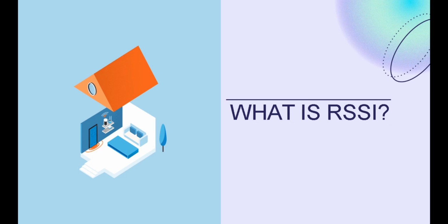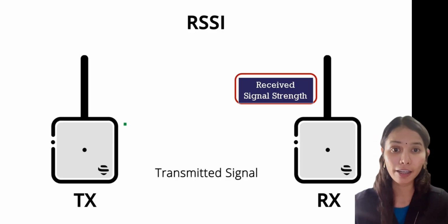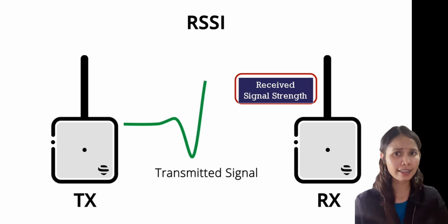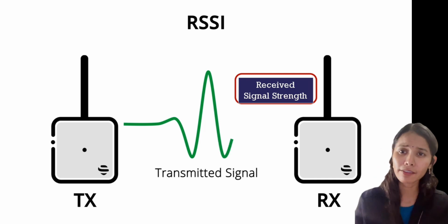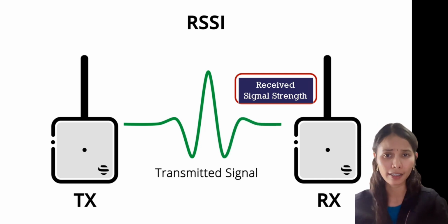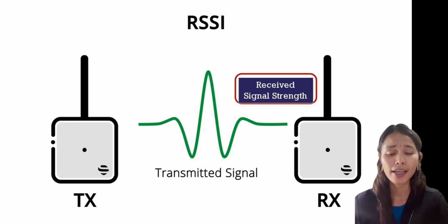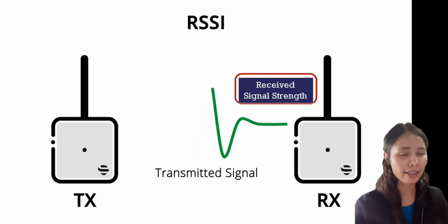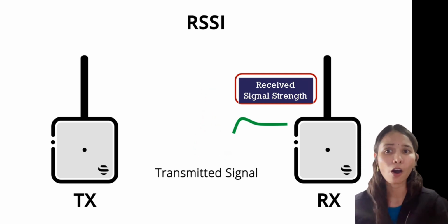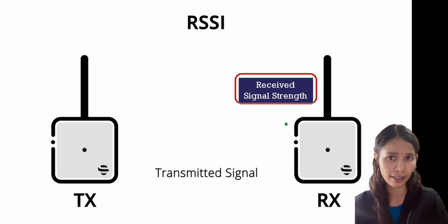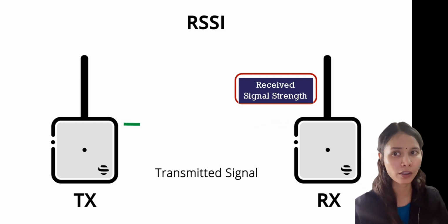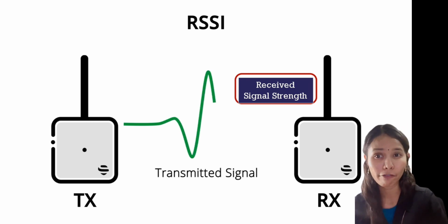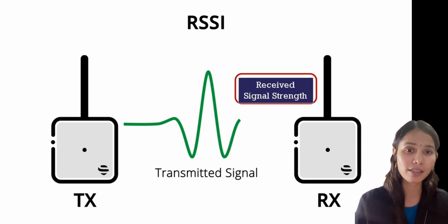Moreover, what is RSSI? RSSI stands for Received Signal Strength Indicator, a signal or circuit that indicates the strength of an incoming signal in a receiver. The strength indicator on a cell phone display is a common example. RSSI is often in the IF stage and IF amplifier. RSSI is also a measurement of how well your device can hear a signal from an access point or router. It's a value that is useful for determining if you have enough signal to get a good wireless connection.